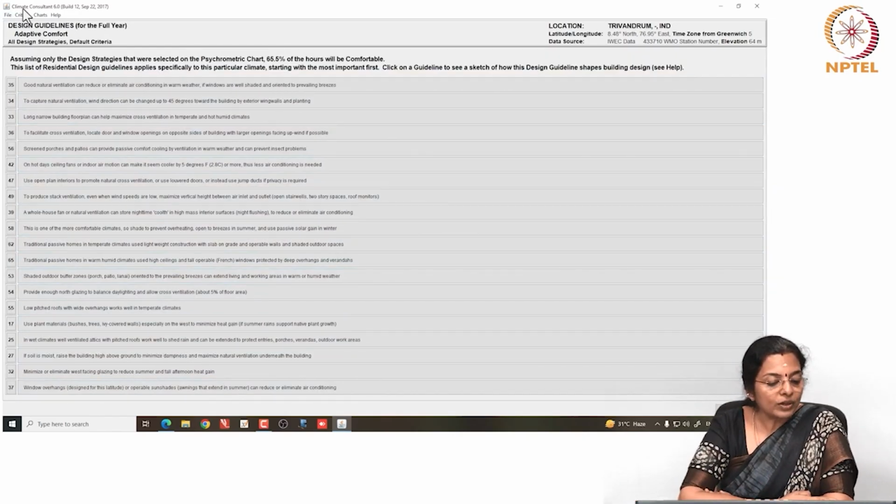So, assuming only the design strategies that were selected on the psychrometric chart, 65.5% of the hours will be comfortable, and this list of residential design guidelines applies specifically to this particular climate, starting with the most important first.